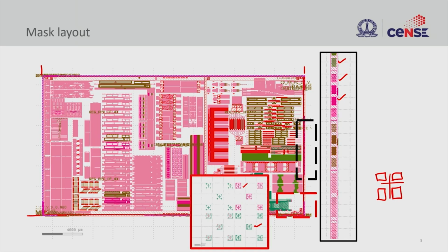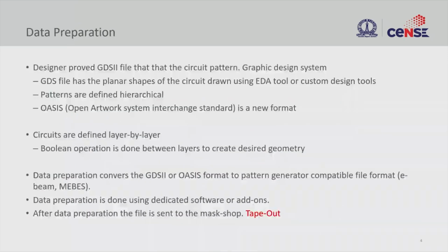So what we do is we put some measurement structures at these edges, what we call the scribe line. These edges could be used for measurement of the structure. Since we are illuminating the whole mask with the same amount of energy, you expect the structure on the scribe line or the edges to also yield the same dimension as you have in the center of the mask as well. All right.